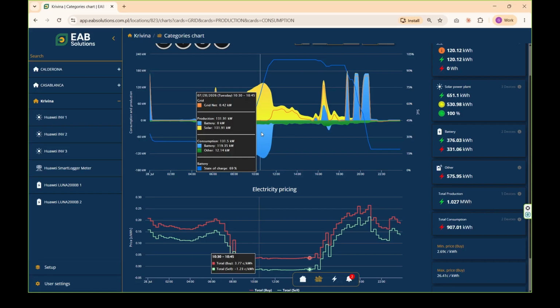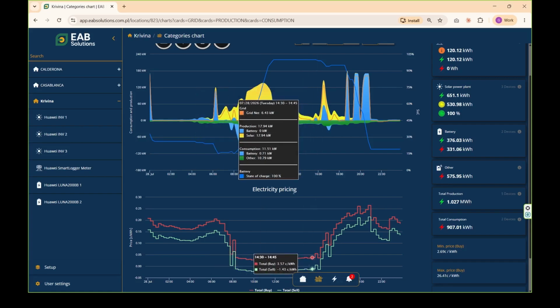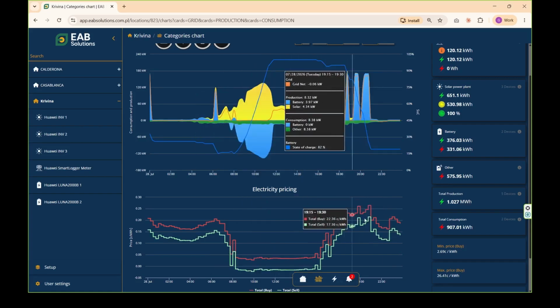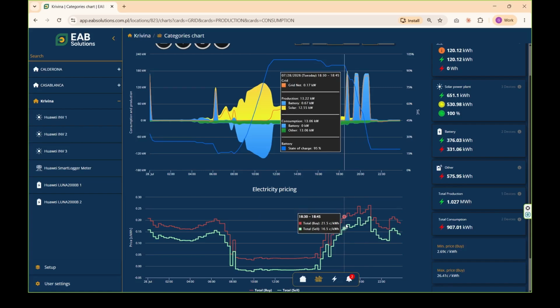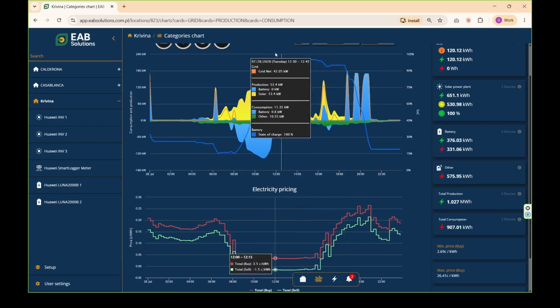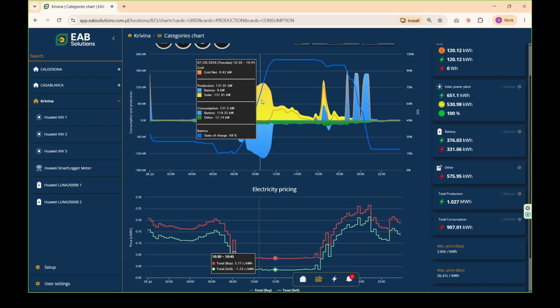So we can organize the day in the EMS to prioritize buying electricity at certain hours and selling electricity at others. What's more, the EMS can perfectly well work out whether it's better, given the electricity prices, and if there's going to be a very strong price at some point in the day, that perhaps it's better to take even the solar electricity, which would normally go to feed our industrial client, and instead of feeding them, charge the battery to make sure we reach the maximum charge, both from the PV and from the grid, and sell it at the moment of highest price.